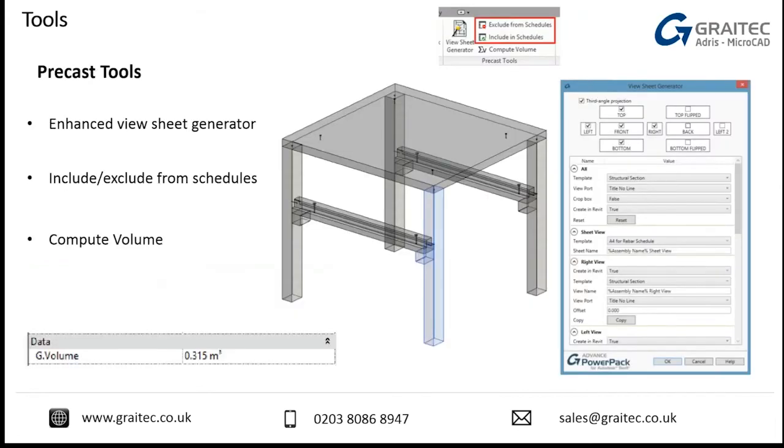We've got some precast tools in there, okay? So if there are any structural engineers that are using precast tools, then we've actually got some additional controls in here. Now, a few years ago we had the assembly tool added in, and not many people have used the assembly, but if you had, for instance, in here we've got the column with the horns on, which is a separate entity, we can merge that into what we call an assembly. We could merge the whole of that view there into an assembly.